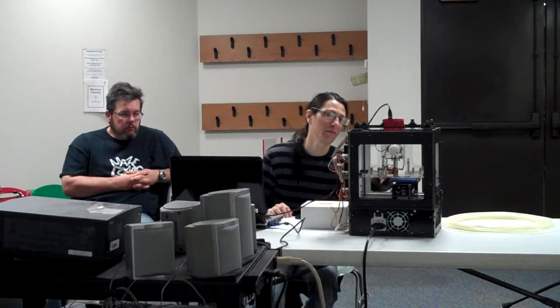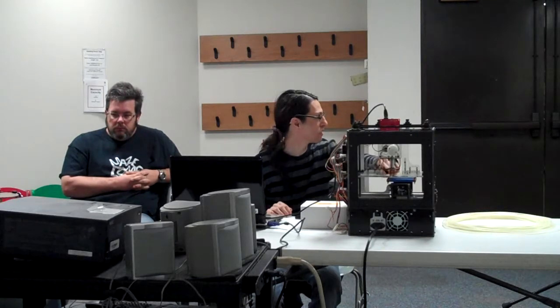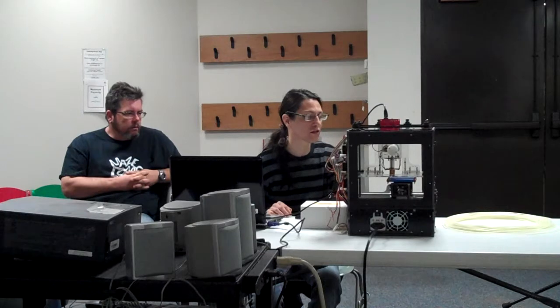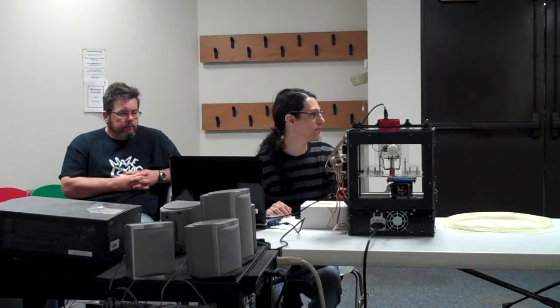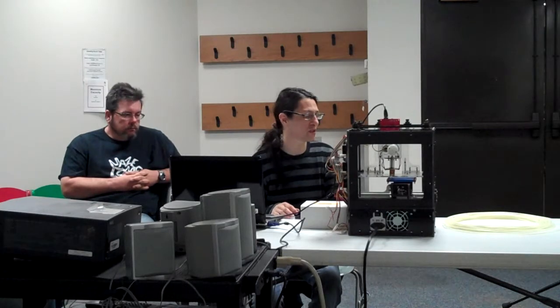So there's a lot of maintenance the machine needs after usage. After the part has been printed, what I usually do, because you have to heat up the element in here, it's nichrome wire. It takes a while to heat up, and you don't want that thing hot all the time, because after a while you burn up that wire. So I usually heat it up, print, and then after it's printed, it starts cooling down.